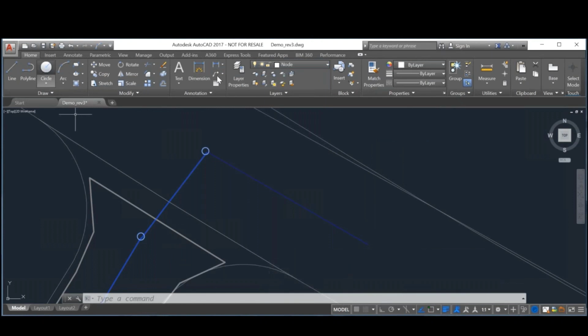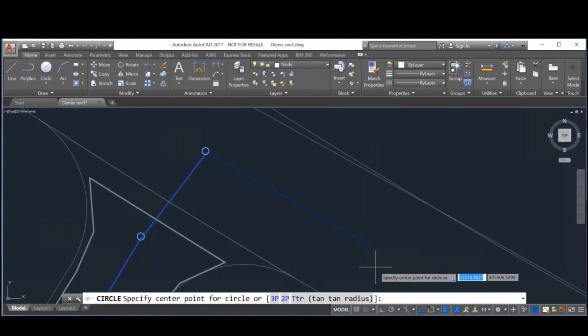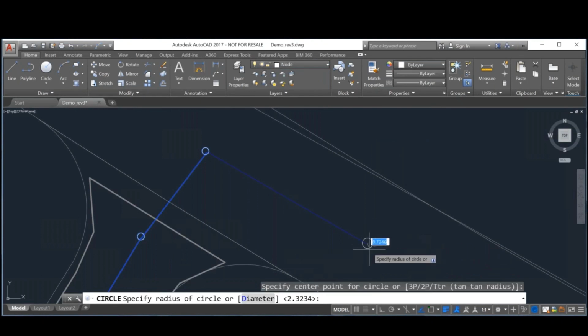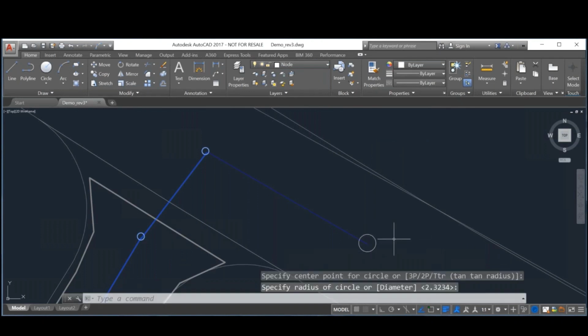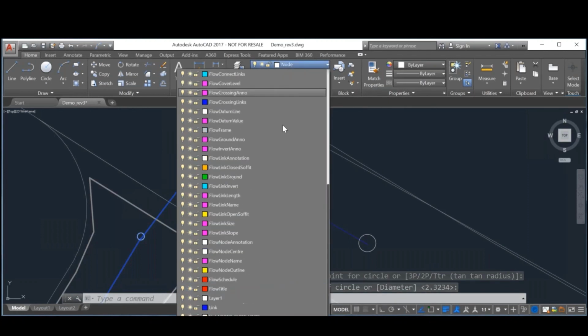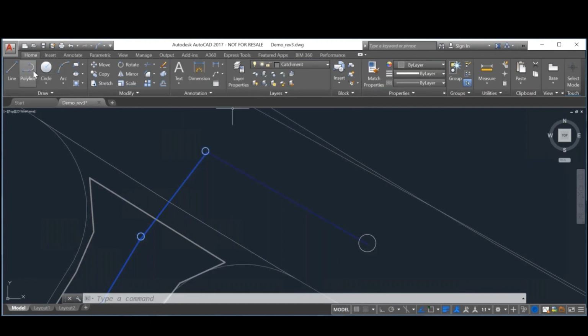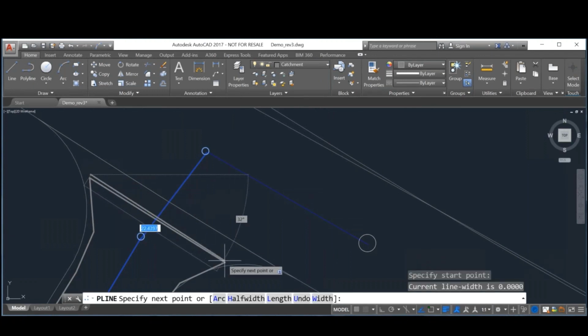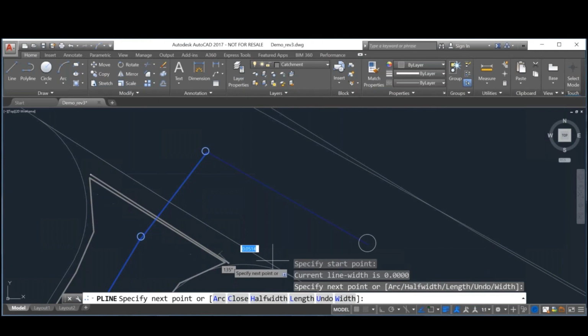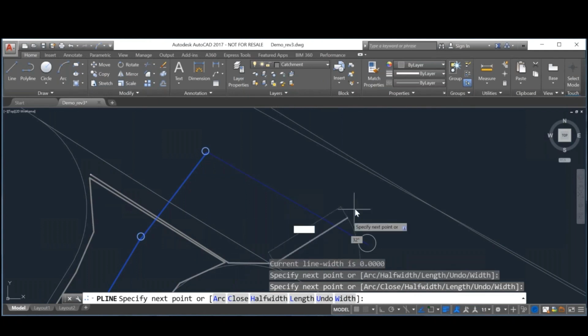So we're using that AutoCAD functionality, and then we're putting in circles for nodes. And then when it comes to the contributing areas, you can use polylines or polygons to define contributing areas. And you can create layers for the nodes and links and catchments in AutoCAD.